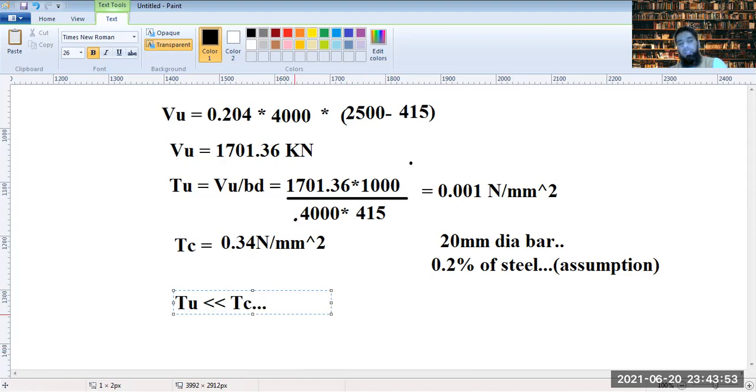So it's okay. We do not need the shear reinforcement in this footing. That's one thing. The other thing is, when you are not requiring the shear reinforcement, we are also trying to check what is governing. But for that, we need to first check the two-way shear criteria as well for this footing. So what we will be next doing is we'll be checking the two-way shear criteria.